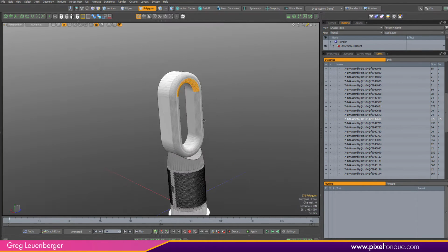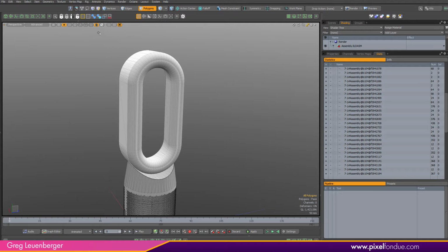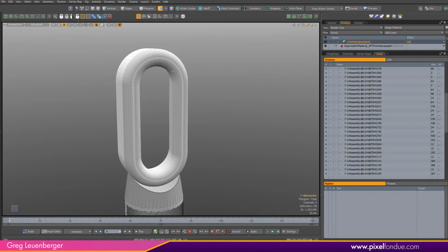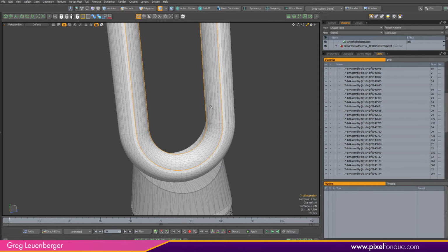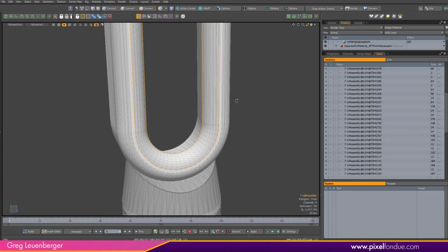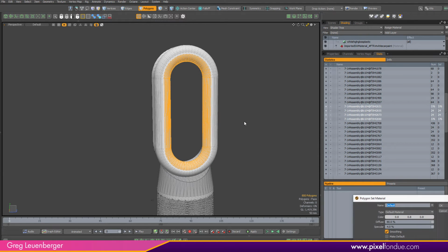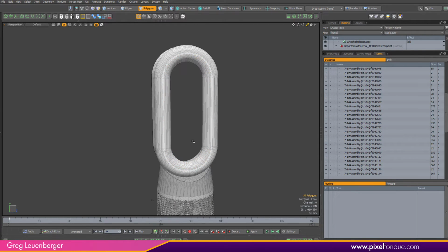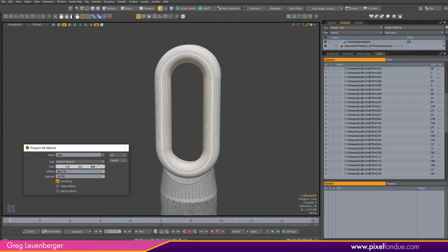Now these are useful in that if you want to do some re-texturizing on here, I can go over to my P tag drop down and select parts instead of materials and press 4. If you hover, for some reason it's not showing up in advanced viewport. Let me just go to default real quick. You'll see the outline right there. I can quickly get this ring by holding down Alt and clicking, and pushing 3 to convert to polygons, then just press M. In fact, I don't even think I have to convert those to polygons. I think I could just grab these. Say I want a different material here, right? So I press 4 and then just select my parts, and then I just press M. We'll just call this red and make it red.